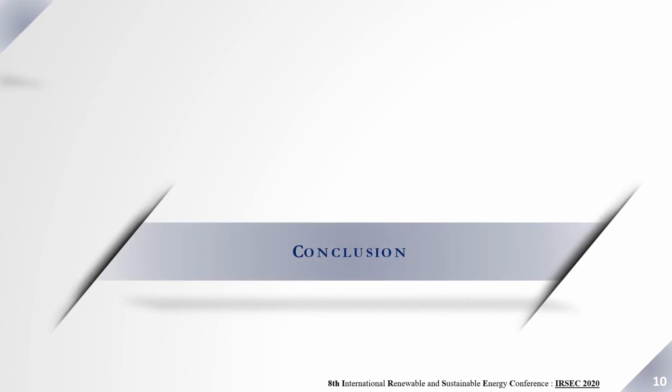The aim of this presentation is to describe the main path of the PhD project by understanding the heat pipes at the microscale, to really get a comprehensive knowledge of the phenomena that could occur like Marangoni effects due to the large change in the surface tension in a very tiny time. Also to master the limitations of heat pipes in general, which could occur when a bad operation of the micro heat pipe is made, like dry out or flooding, as an example, or when the vapor reaches its sonic velocity, and this kind of limitation we call the sonic limit.